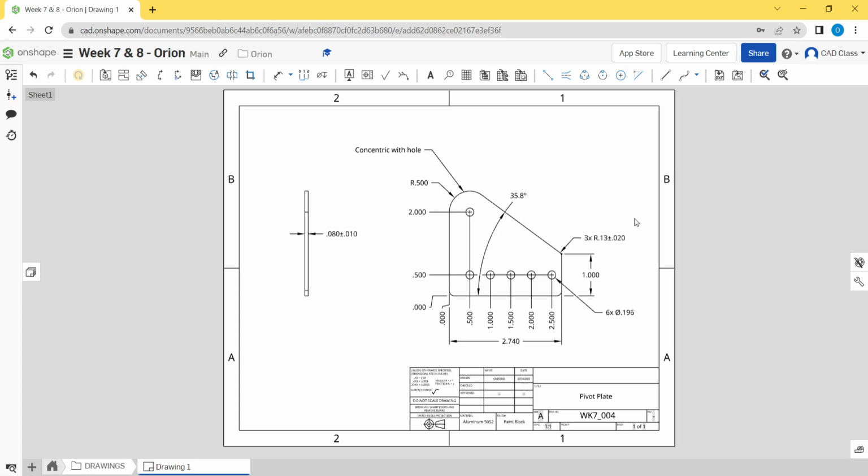And so generally speaking, the tolerances in FRC are so loose that the machine that's making the part, whether it's the mill or the lathe or the router or the 3D printer, those are all more precise than the tolerances that we would need to set. So it would be extremely rare for the router to cut a part so far away from the CAD model that we would need to remake the part or something. The one exception to that is when we're cutting parts that have bearing holes in them.